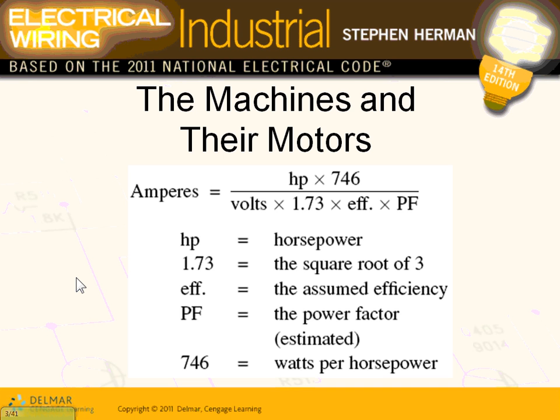If you don't understand, this is one of the most important formulas that you guys have. You have them also in DeWalt. All these formulas about motors are in DeWalt. Tons of, I think, very, very important ones. If you guys go to page 1-4 in DeWalt, all these formulas are there. This is one of the most important formulas that you're going to find. Based on the horsepower, the voltage, the power factor and the efficiency, I can find the full load amp of a motor.